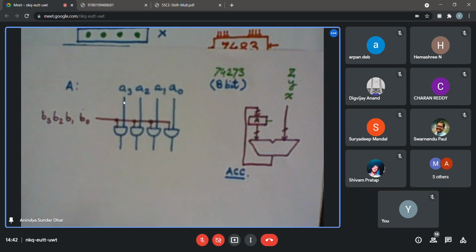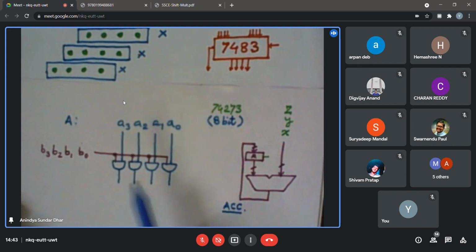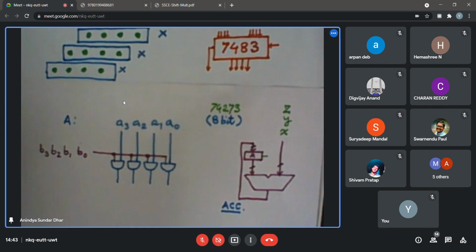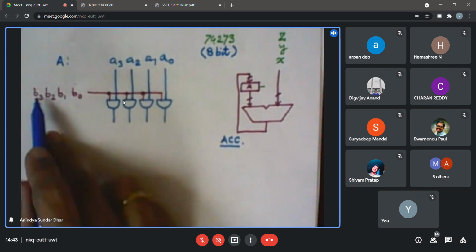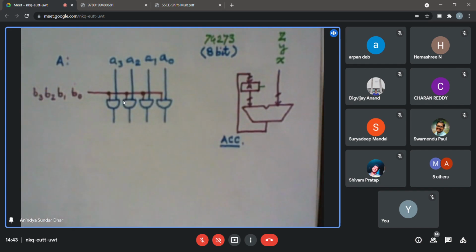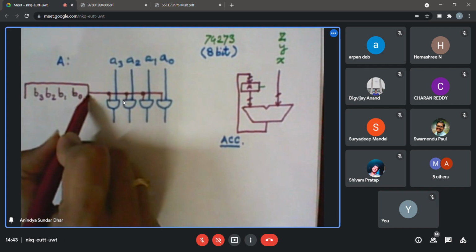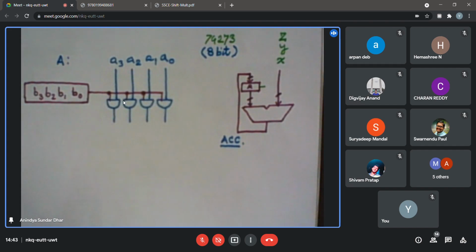Since we have already drawn the structure, it might be apparent how you generate those partial products in place, then I will come to the accumulation process. As I have already drawn, initially you may need to give B0, then B1, then B2, then B3. So what if I store it in a 4-bit register, and then the last bit, meaning the LSB, I connect to the common input of all the AND gates. Will that serve the purpose?